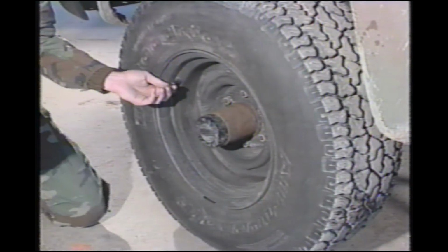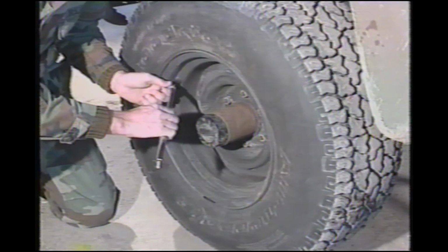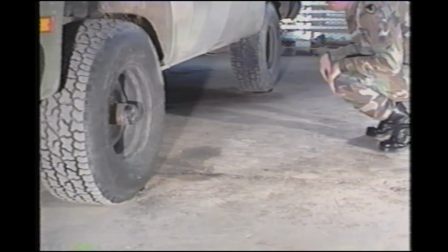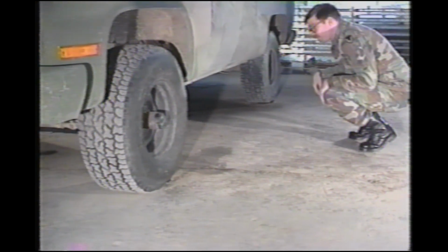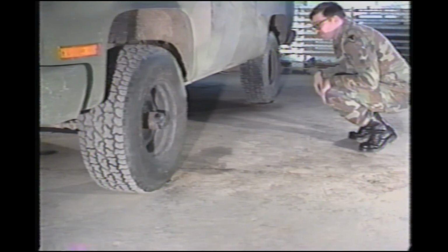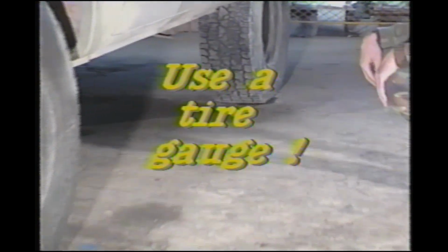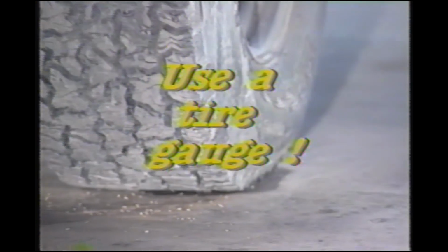Tire pressure cannot be judged by how flat the tire appears. With tires, looks can be deceiving. Radial tires may look low even if they are properly inflated. The tire on the front is correctly inflated, while the one on the rear is 15 psi underinflated. The underinflated tire shows little change in sidewall flex. You must use a pressure gauge for an accurate reading.